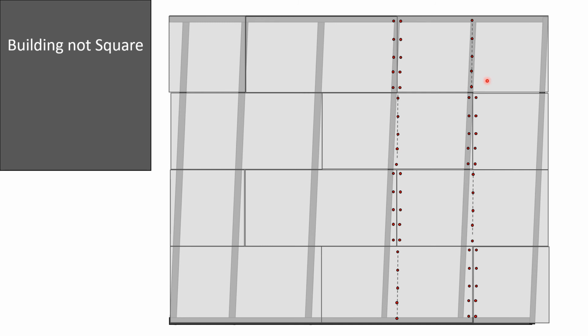But I've run into problems similar to this, not this extreme, but you would have to go back and cut a piece of wood and nail it to the joist here to have something to nail to up there. When something's out of square, it's going to cause problems. The building can still be built, but things are not going to look as good, and you're going to have some structural problems that are just going to cause you a lot more work.